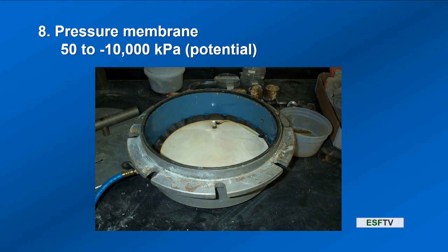So this is the way to develop that soil moisture characteristic to getting those very low potentials and lower than that. And it's all done with compressed air or compressed nitrogen, a pressure applied to the sample to equilibrate the water held in there at whatever soil potential we're trying to make the curve for.